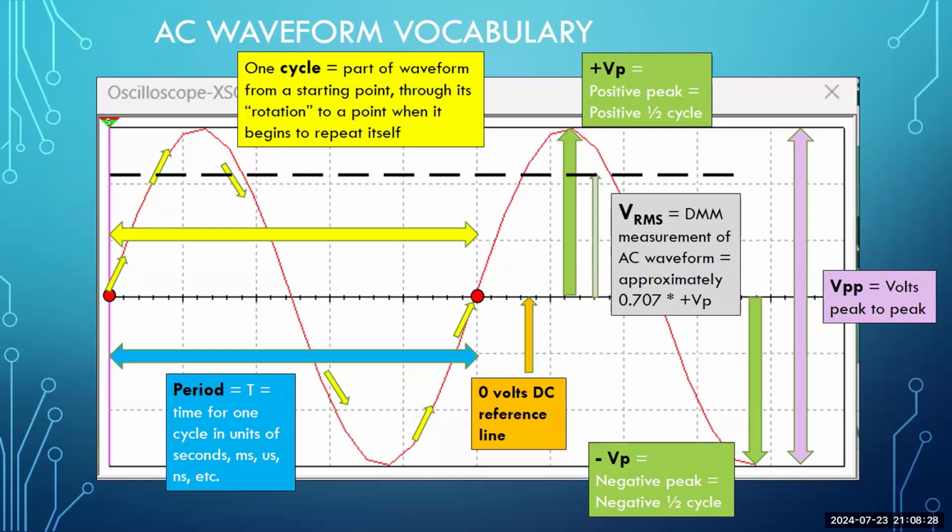The digital multimeter we've been using through all of the DC topic YouTube videos will be able to measure an AC waveform, not graphically like this oscilloscope, but it will be able to measure the AC value. How much AC is measurable on a digital multimeter is in a form called VRMS. And to calculate it is very simple.